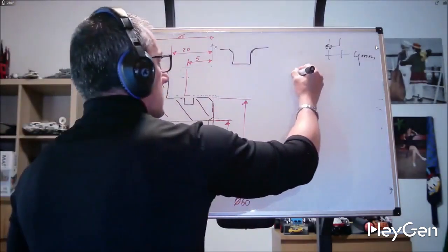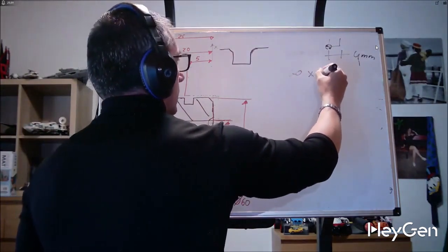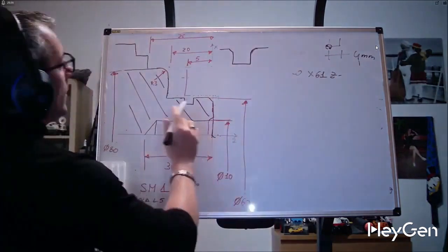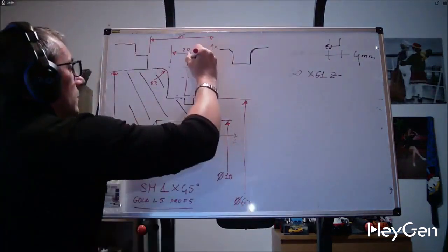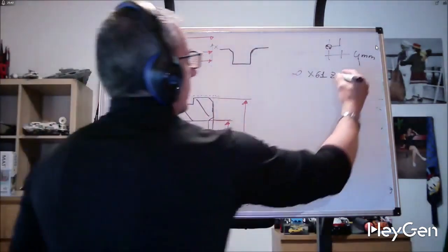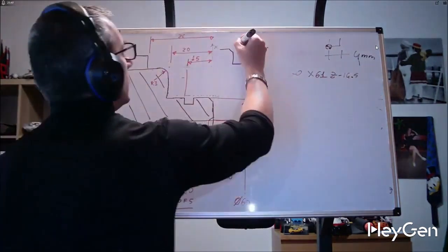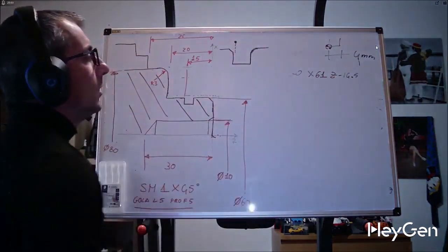Let's call the cutter, put in all the cutting data, generate it, M4, and in G0 we move to X61. I wrote Z5, but that's not right. Let's go to Z, at least 14.5. So we position ourselves here, more or less, then we tell it.